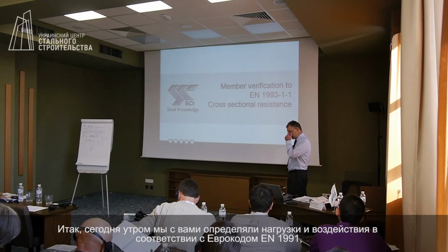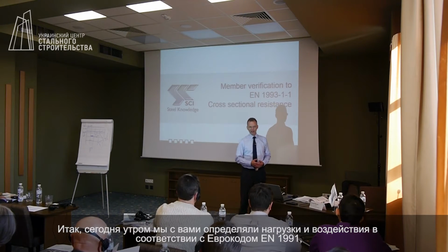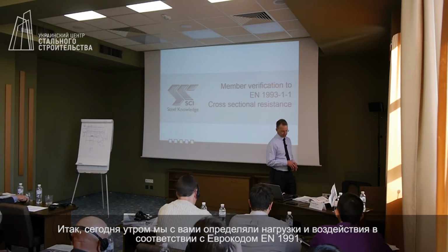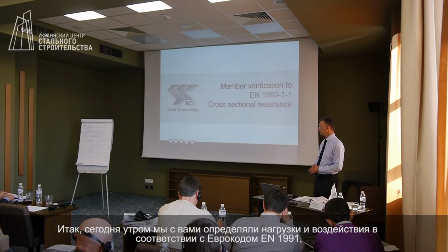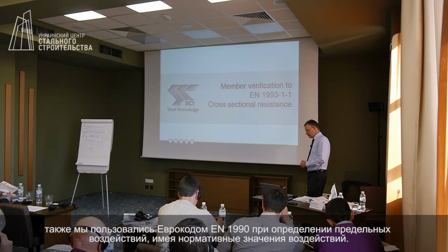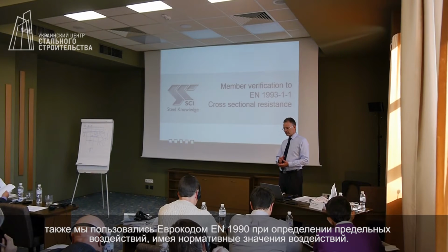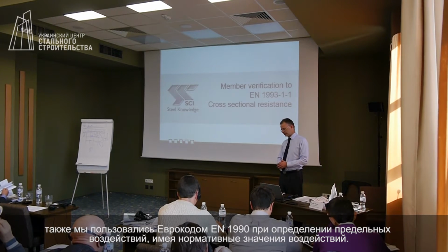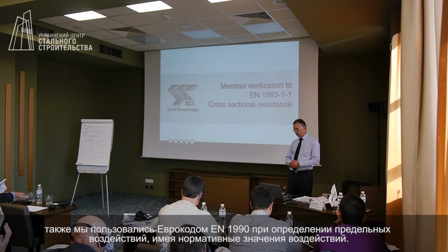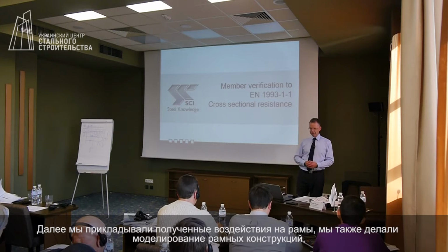Okay, so what we did this morning is we determined some actions, first of all, from somewhere in the 1991 suite of codes. We then used EN 1990 to convert those characteristic actions into ultimate actions. We applied them to the frame somehow, so maybe we did some modelling of the frame.